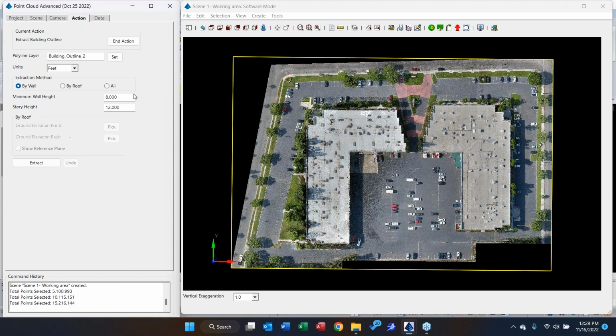We're gonna tell you this was processing feet, US survey feet, and so on. But when it comes from a ground scanner, many software packages like Cyclone, Vectorworks, etc., will send it over in metric. You want to do a conversion. But if you don't, let us know: hey, I'm working in feet or I'm working in meters. The point cloud is in feet or in meters. In this case, it's feet, right?